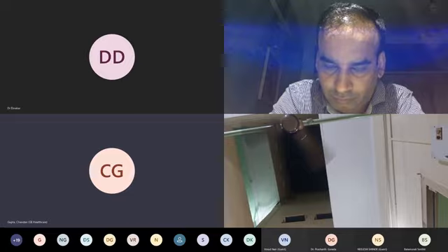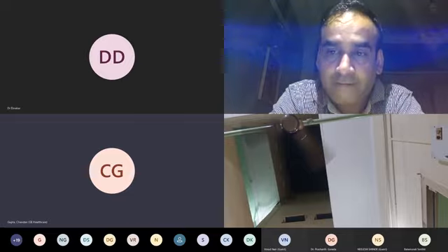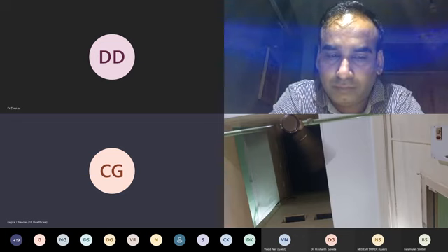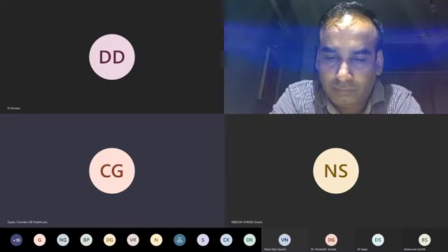Now you look at it, when you use a warmer, it is a direct heating. When you are doing a direct heating, heat is coming directly to the baby and the temperature is changing. So the PID controller is good in a warmer environment. But when it comes to an incubator, your heater is not directly hitting the baby. The heater is hitting the air. The air is going inside a big chamber, and then with that the baby is getting heated.